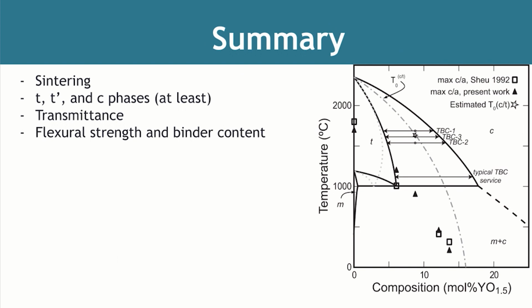So to summarize, it's important to be sure about the sintering temperature of your furnace. Generally, you should consider calibrating your furnace and keep an eye on this. When evaluating the phase fractions of yttrium-stabilized zirconia, we need to evaluate both the tetragonal prime and the cubic phase at least, and perhaps even more phases, although this again depends on the quality of your instrumentation.